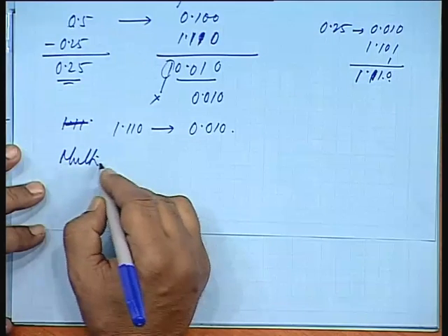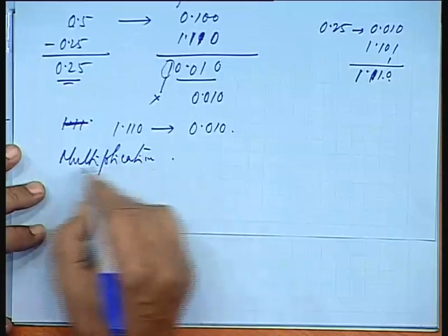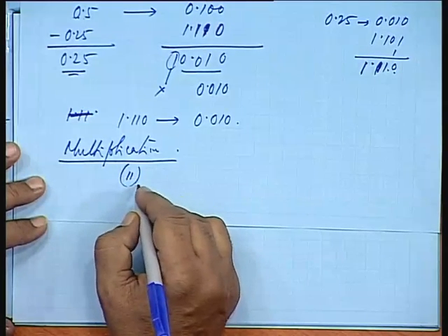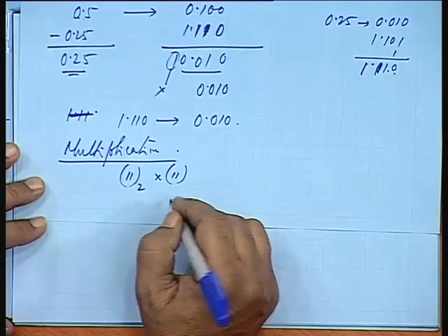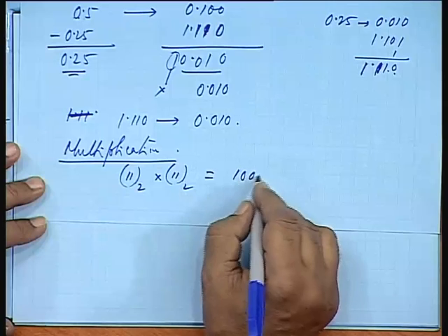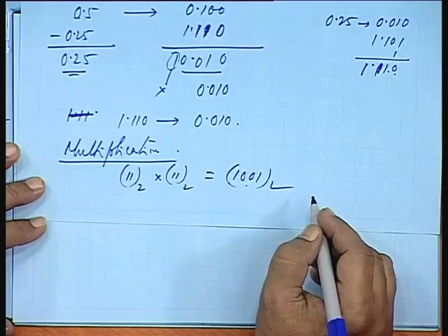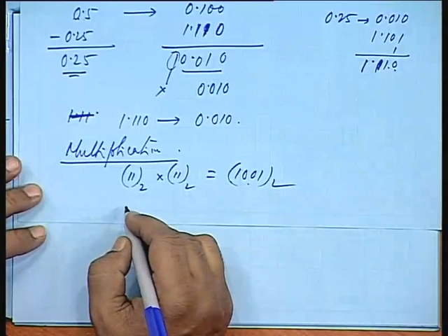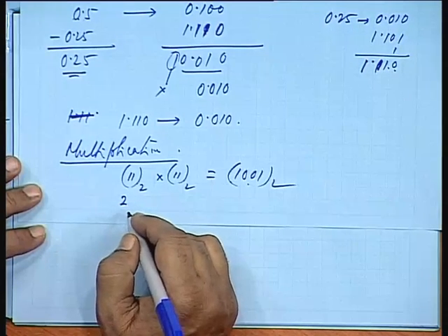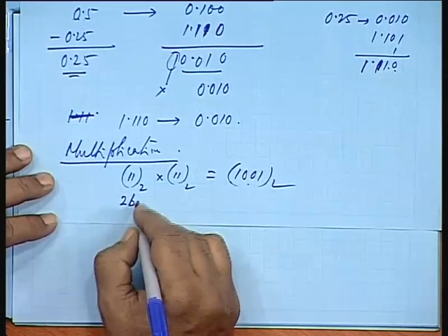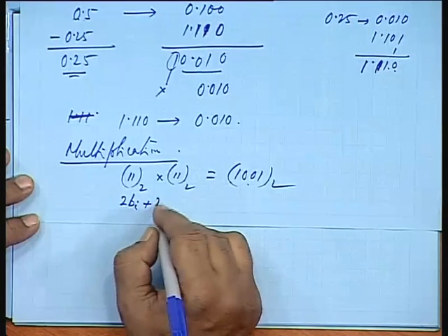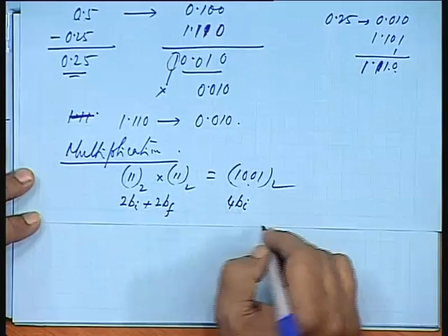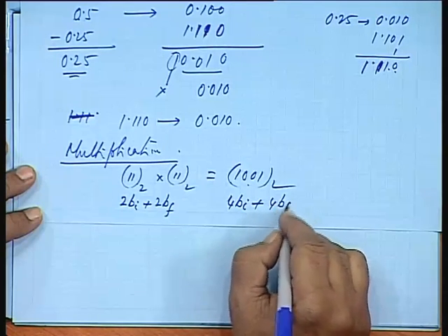Multiplication, this is somewhat involved. We see that suppose we have a 2-bit representation of two numbers, the product is a 4-bit number. When you multiply specially, you get this problem. So, if you have 2-bit number for the integral part plus 2-bit number in the fraction part, then the product may give you 4-bit part in the integral part and 4-bit part in the fractional part.